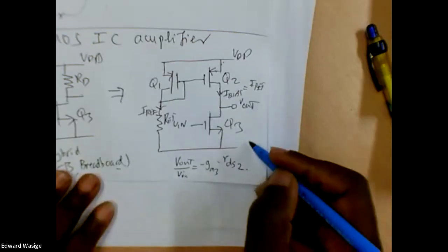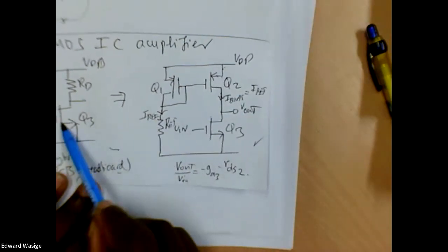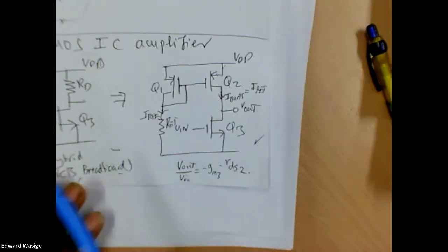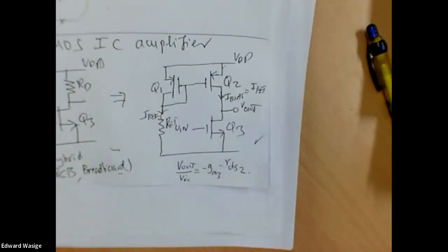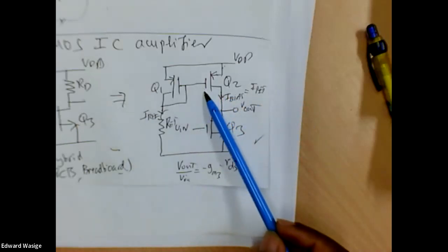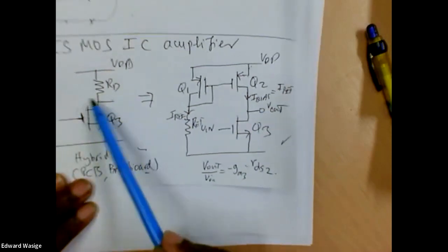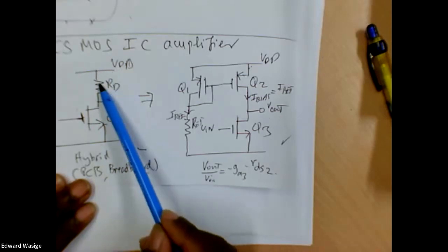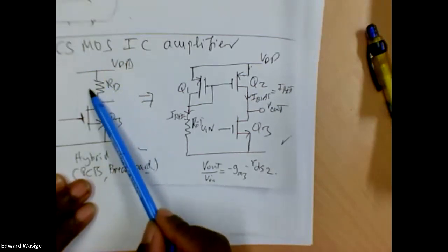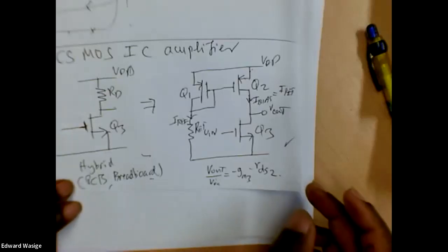So in IC, we do that. On breadboard, we do this. So in IC, we don't do our amplifier like that, but we do it this way. So one little question to the class is, for here, I could only use a PMOS current load for the common source amplifier. I couldn't use an NMOS current mirror to replace this RG. And could you try and find that out?